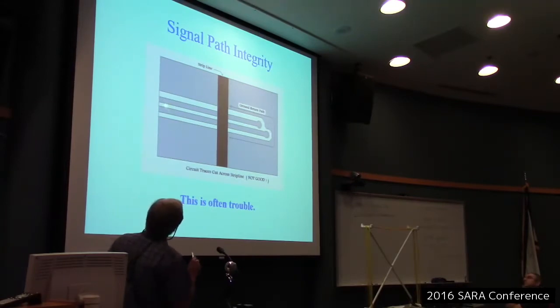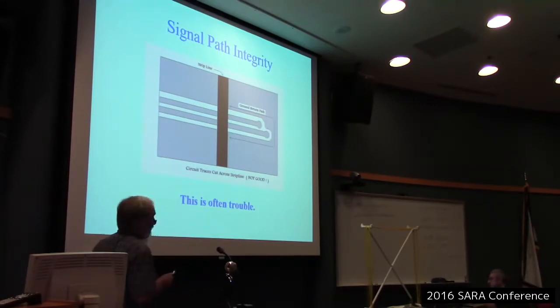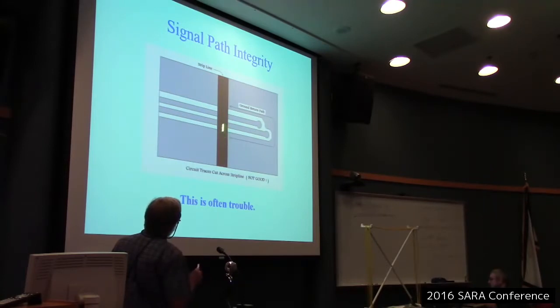So this is an accidental slot antenna to some degree. I'd actually seen problems like this when doing FCC Part 15 testing on a product I was involved with, where I wasn't watching the draftsman very carefully, not giving the draftsman enough baseball cards, another story. But anyway, we had a trace running a high-speed clock, and there was a little slot in the ground plane, and the 10 megahertz clock was everywhere when we started running it. Fortunately, it was found before it went to the test lab, and it was fixed.